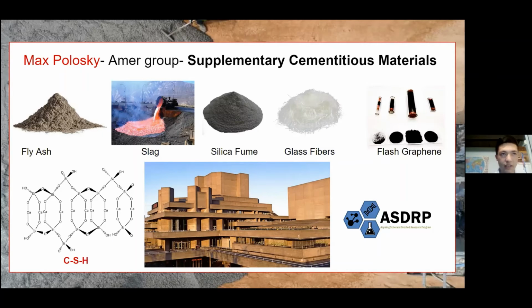First is Class C fly ash, which contains higher calcium concentration and has cementitious properties, and it's able to replace about 20 to 35% of cement in weight. The second type of fly ash is fly ash Class F, which is actually a pozzolan, mainly consisting of alumina and silica, meaning it can replace only about 15 to 25% of cement in weight.